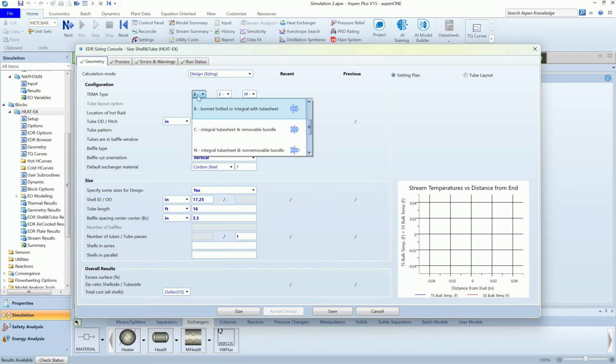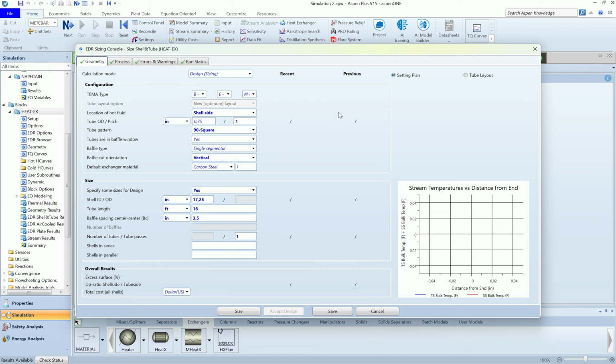For our configuration of the heat exchanger, I think we need to change here. Okay, we're going to use... let me find here. This is the standard, but we are going to be rating, and now yes, we can define here the number of tubes, 166.